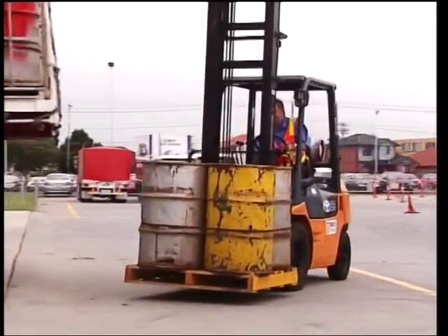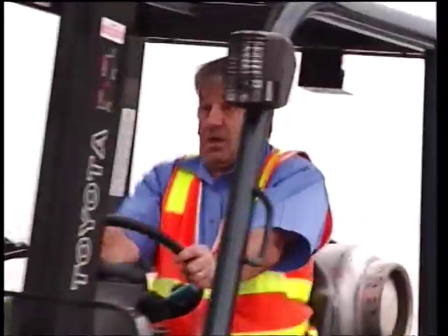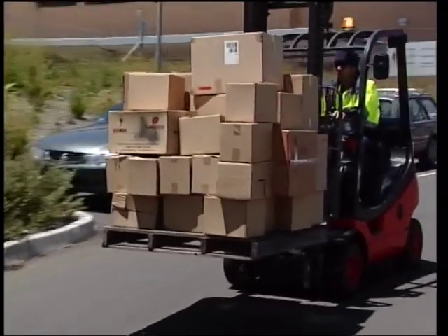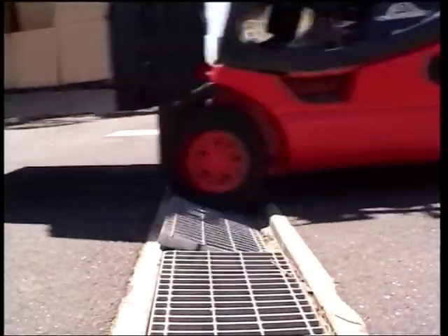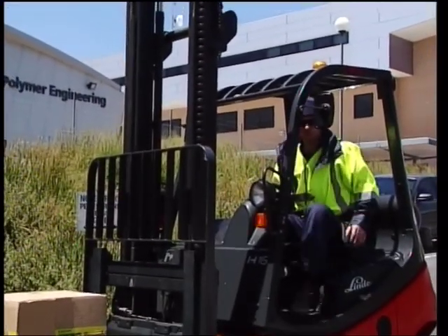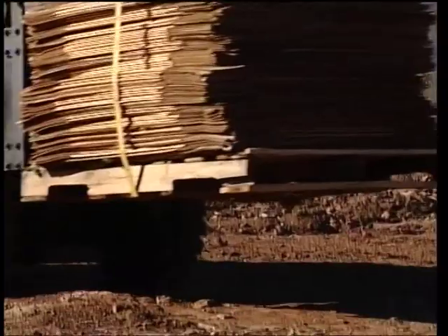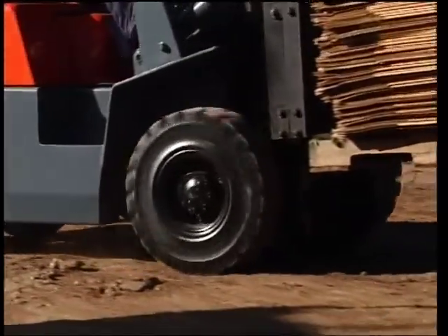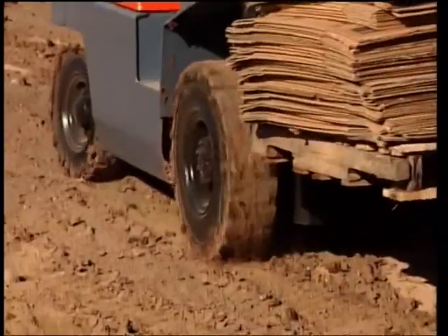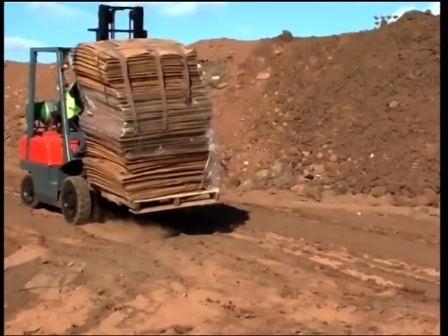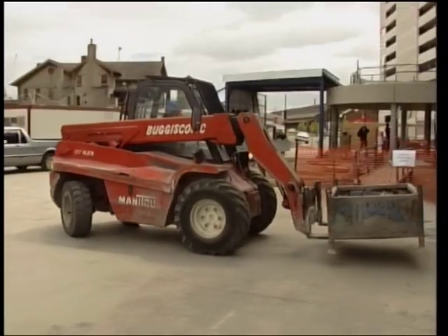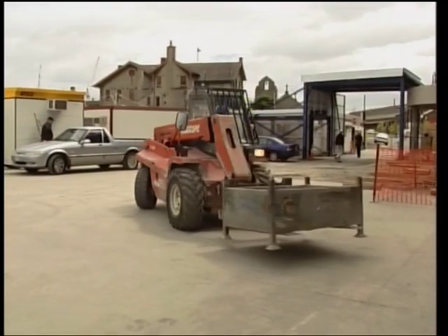Uneven floors, rough terrains, loose objects, bumps or depressions can cause instability. Avoid driving over loose objects or on surfaces with ruts and holes. Most forklifts are designed for hard level surfaces. A soft dirt surface can cause a wheel to sink and destabilize the forklift. Only specially designed forklifts are to be used on unsealed surfaces.